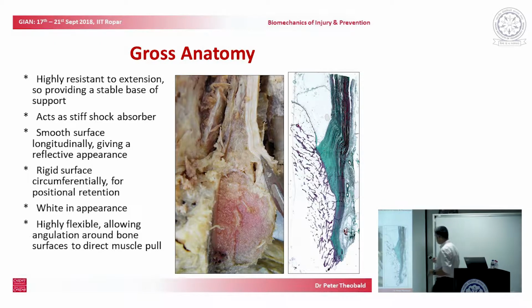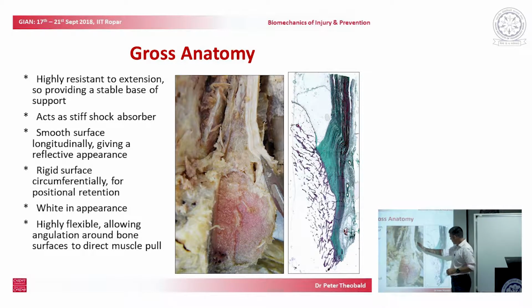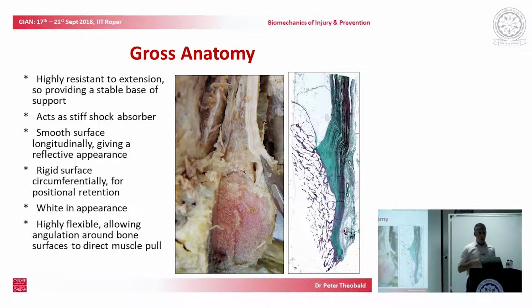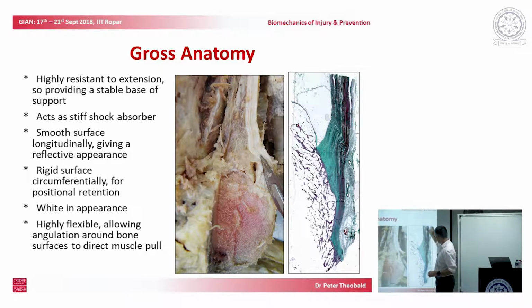One of the challenges comes because inevitably this tendon will curve. As the feet point upwards, the tendon has to change shape. When the feet point downwards again, they change shape. Now, one issue was if this was a single structure, you would have a compressive stress on the inside, and a tensile stress on the outside.